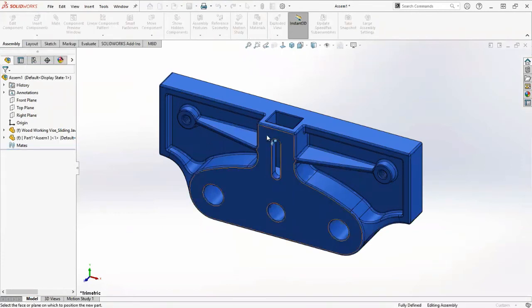Okay. Now the first thing SOLIDWORKS wants us to do is define a face to begin sketching on. This is going to be that first reference part. Think of it as like the top, front, or side default plane of an original part by itself. So I'll select this face.